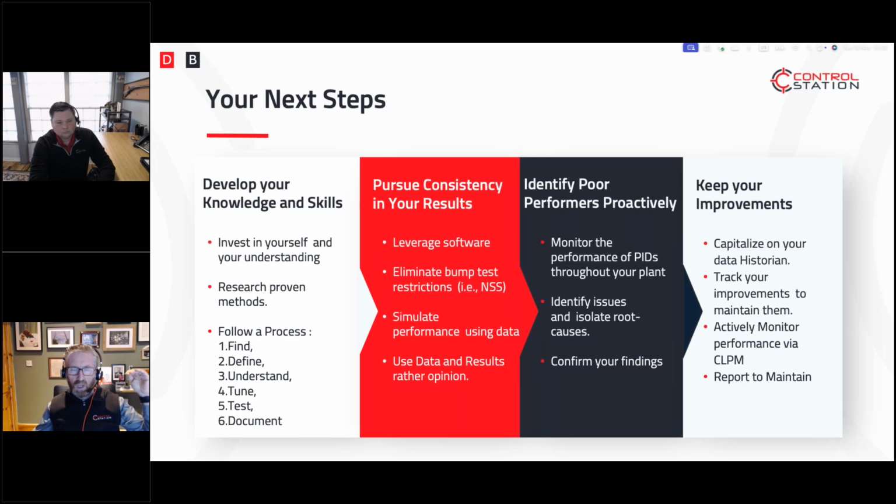Why am I here? Look at the trend, talk to ops, understand where the problem is, then do some testing to find out where my limits are, and use that to start making decisions. You may come up with a decision: there's a problem in this loop. It's a valve. There's a mechanical issue here.